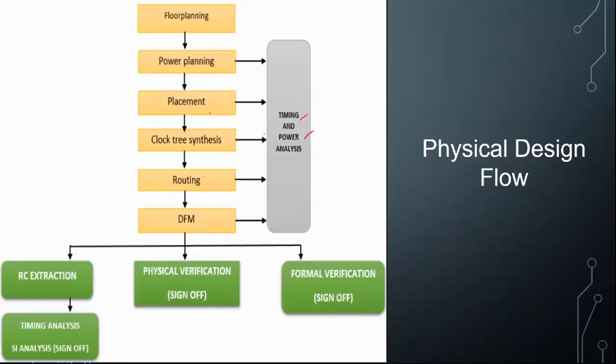Once that is done, we have to go for CTS. CTS is nothing but clock tree synthesis. Here we have the sequential elements, the mux, the flop, and other sequential elements also. In your digital design, for each flop we should supply the clock. That is what we will do at CTS. We will build a clock for all the sequential elements in the design. Once it is done, then we'll go to the routing.